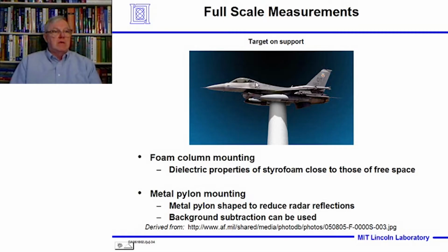Now what you do typically is you'll take the target. In this case, this is just a photograph of a fighter, an F-16, and it's just on top of a pylon. The pylon you make out of dielectric foam, very close to the dielectric properties of free space. So effectively, it's structurally sound, a solid pedestal, but electromagnetically, the electromagnetic wave that hits it won't see it.